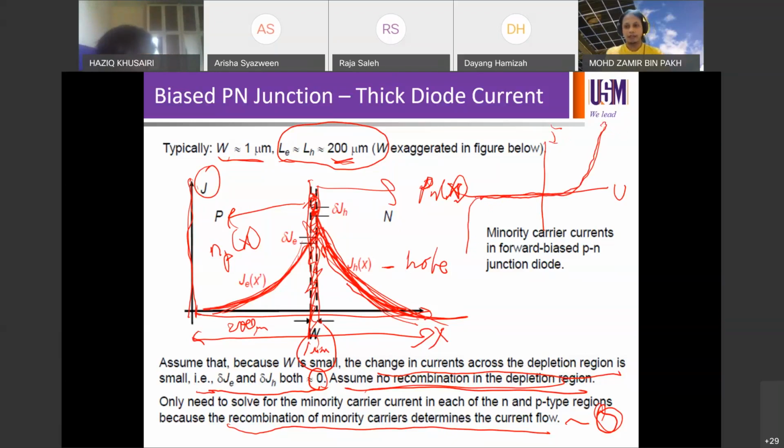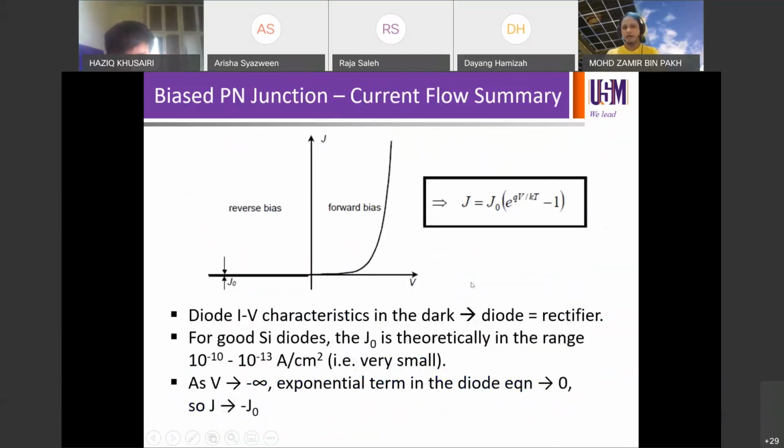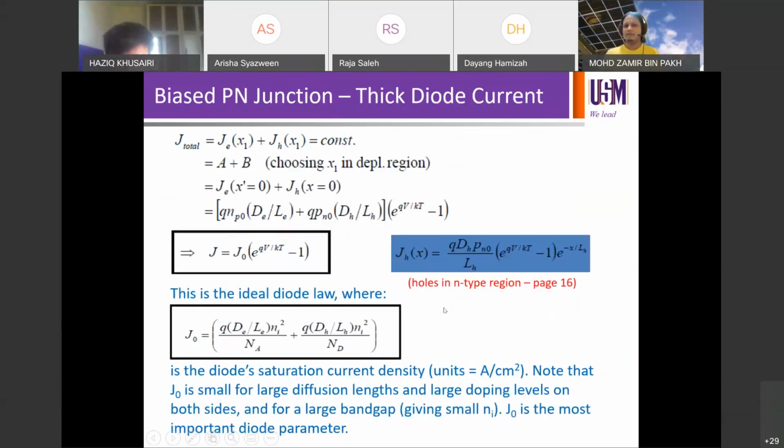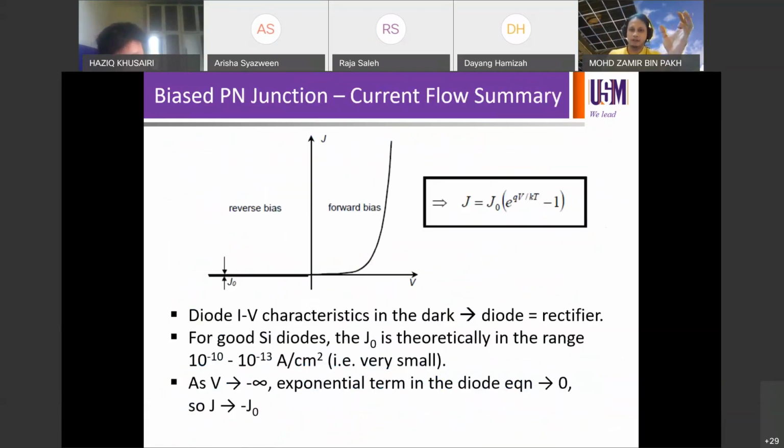So we're going to learn later on how this is going to affect the diode equation, okay? So this is the diode equation. We will learn it tomorrow, insyaAllah. So J equals J naught e to the power qV over nkT, and you also learned about the ideality factor, right? Diode ideality factor. Have you learned it? Remember? Forgot? So when you learn about electronics, you are learning about the diode equation: J equals J naught times exponential qV over kT minus 1. And that's it, right? That's it.